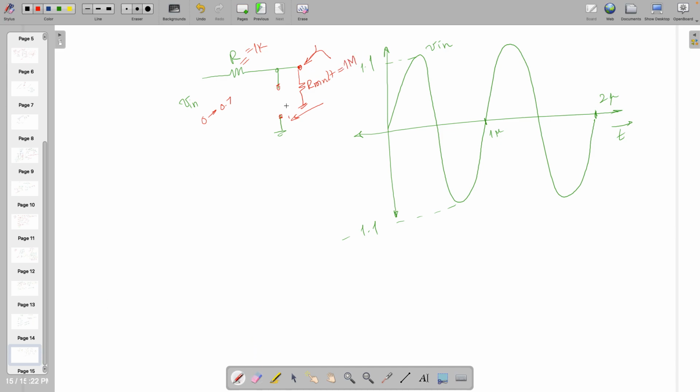So at this multimeter point, what I am going to see is R mult divided by R mult plus 1 kilo, times V in. R mult is replaced by 1 mega, right? So 1 kilo is very low, so you can cancel both of them. So on the output side you have V in only, with some small negligible error.